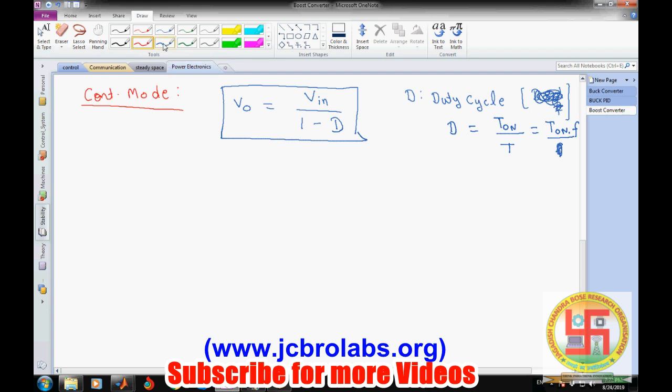Then the inductor values. Another thing is what the inductor value should be. If no load condition is specified, or the specifications are given in terms of the ripples in the inductor current, then the inductor value can be given by this particular formula: L equals V input into D divided by delta IL into frequency.